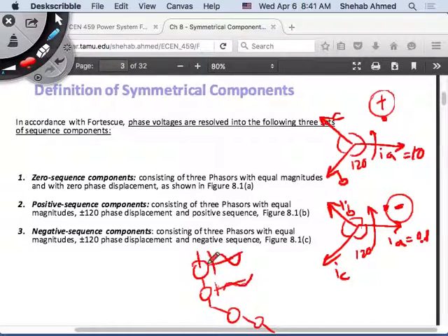And what will be the voltage at the terminals of phase A, between phase A and neutral? Come on, it will be the sum, just a series sum of the two sources. So you can actually emulate this in practice.